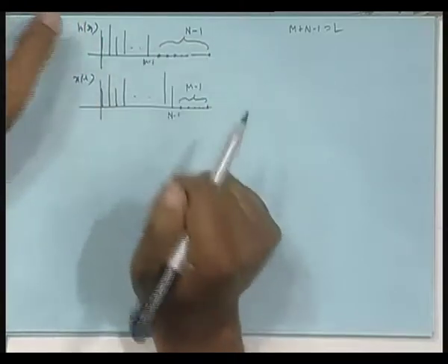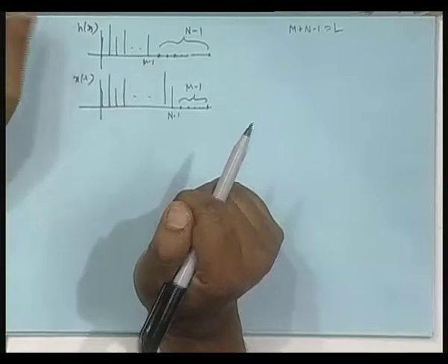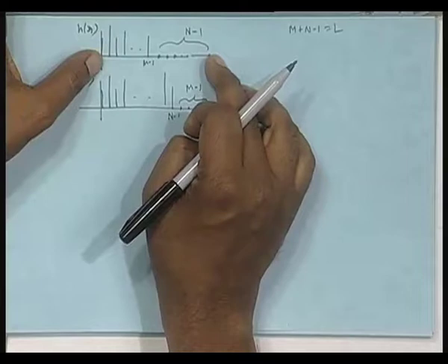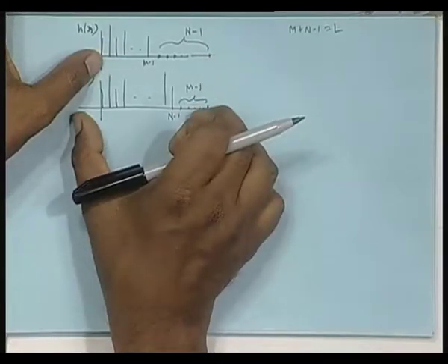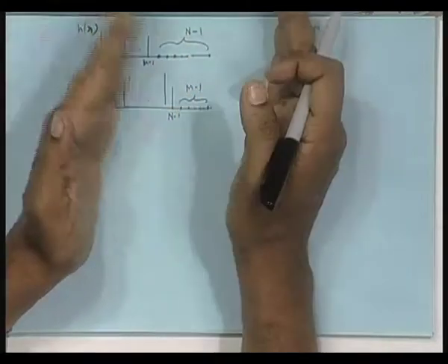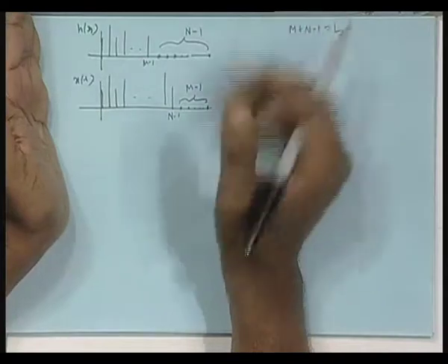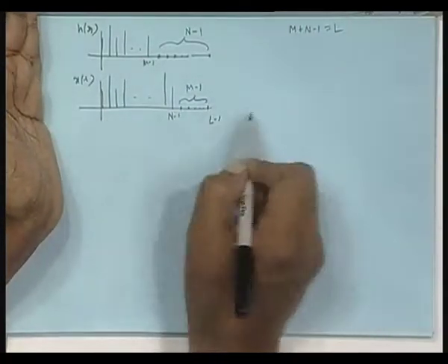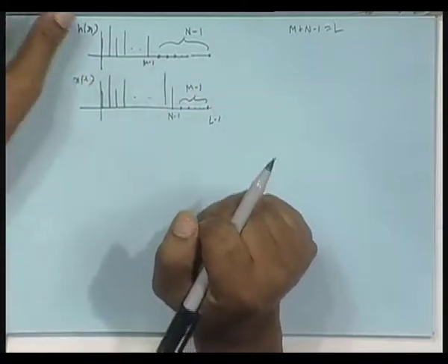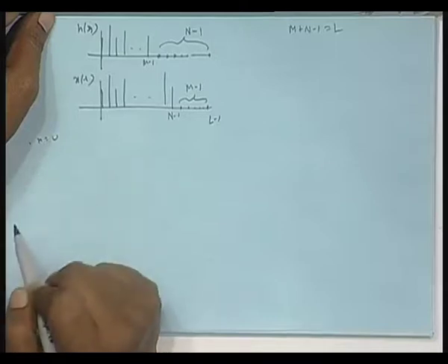I want to now do circular convolution between the two. Okay. Very simple, I will follow the graphical method. I will hold the top one as it is, make a periodic version of this, reverse, shift, and then chop off the right side and left side, right of this point and left of this point. This point you can call L minus 1, 0 to L minus 1, length is L, and then sample-wise multiplication and addition. So, if you do that for 0 shift, say for n equal to 0, what will happen?